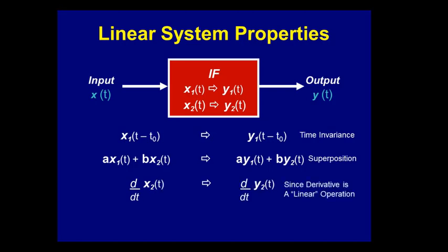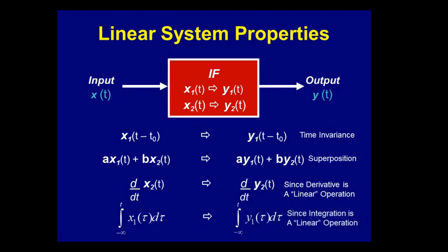And because derivatives and integrals are also linear operations, if I know the response of the system to some simple function, I know the response of the system to its derivative or to its integral. I just take that same response and integrate it or differentiate it, whichever operation I did to the input. So I'm going to push this superposition for all it's worth.